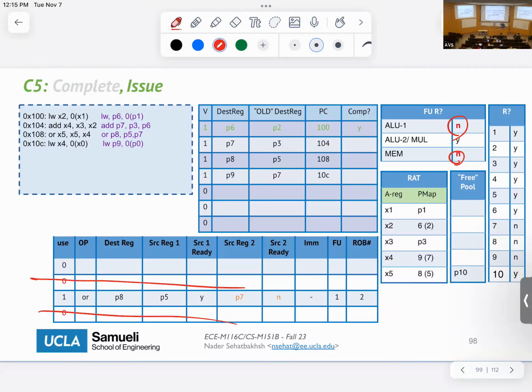And then what will happen is that this is a continuous sequence of instructions. I'm not showing future instructions here, but you can imagine that the pipeline is always filled, right? So you fetch and decode the next 2 instructions, and then you push those into your reservation station, and so on and so forth. I'm just showing a snapshot of 4 instructions in the pipeline. Of course, this is not always 4. There's always a huge sequence of instructions in your pipeline. So we continue doing this.